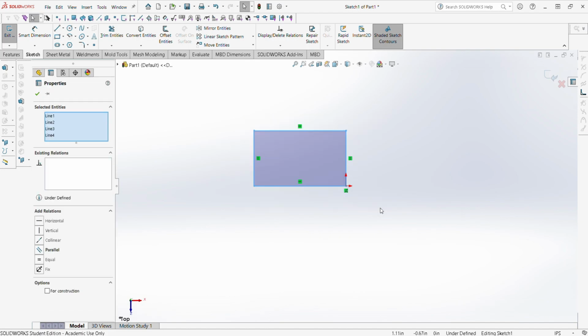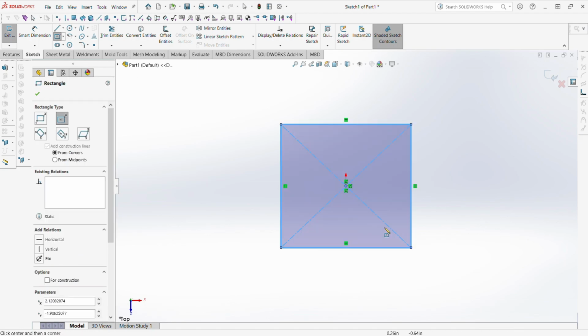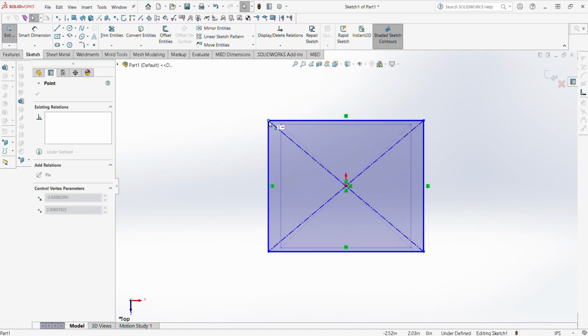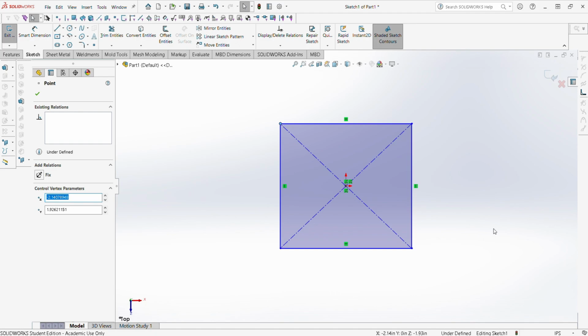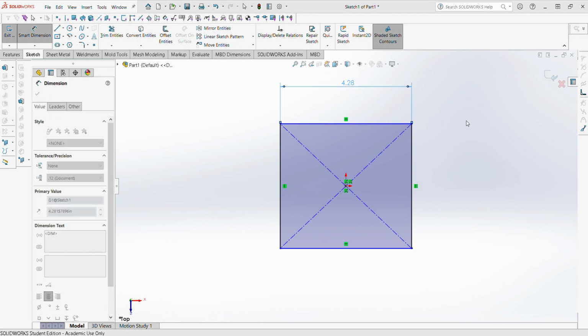What I mean by that is if I were to do the center rectangle, you see all these restrictions or constraints saying this is coincident with this, this is equal to this, all sorts of stuff. It's handy if you want everything to be in line with itself. But anyway, I'll just get into the dimensioning. This is called your smart dimension. I just do smart dimension, and you just click the line, and you click again, and it says, hey, how long do you want that?